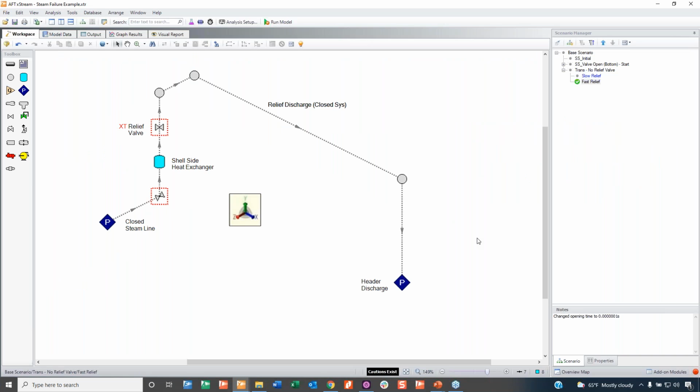Okay, so let's pull it up. Since we're looking at forces, and the reason you would care about that typically is to export those to then do pipe stress analyses. So load your force files into your pipe stress program. That is all going to be three-dimensional. So here I've drawn an isometric view of our system, and I have a coordinate system according to my pipe stress program. Because in AFT, it doesn't matter.